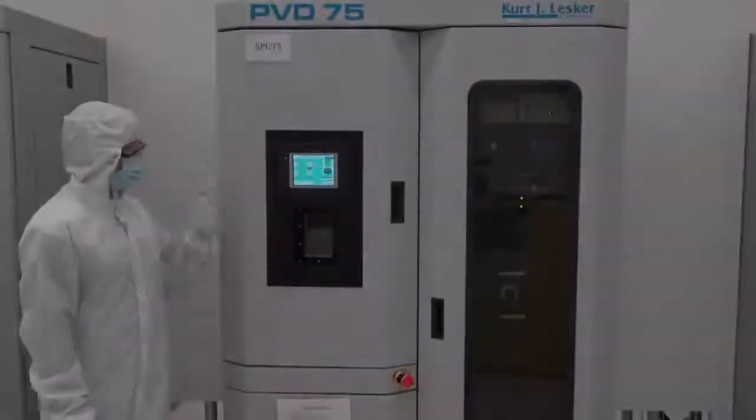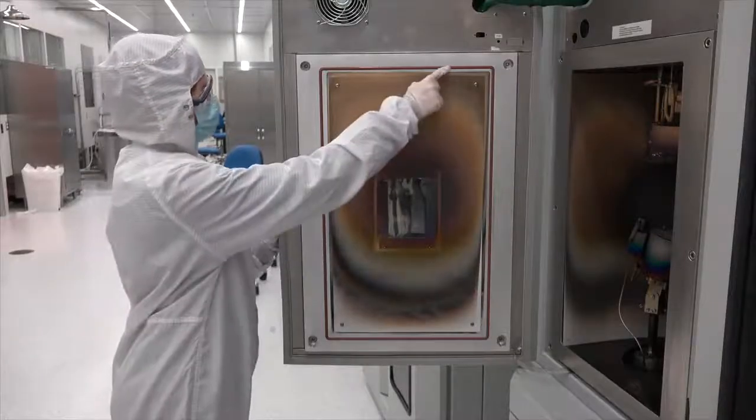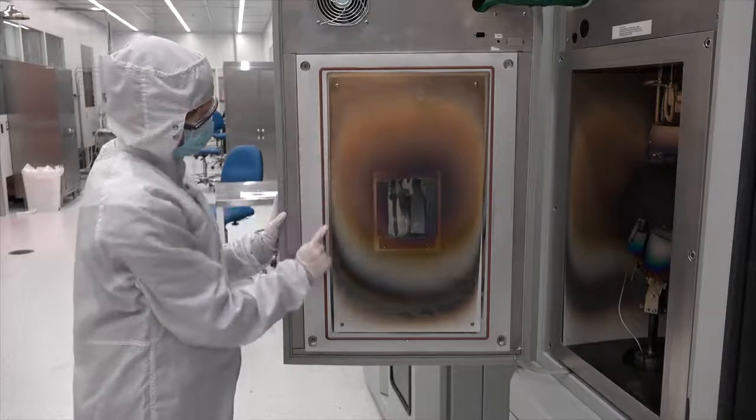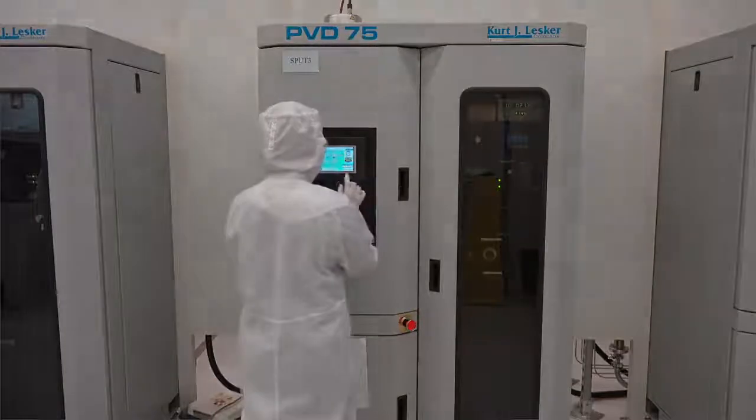Hey, Callie. I understand that you're making some photodetectors in the clean room today. Now, a photodetector is an electrical device used to detect light and output an electrical current. Callie, can you take us in and show us the vacuum system that you're using to deposit the contacts onto your photodetector? Sure, I'd be happy to. Let's gown up and go into the clean room to see the system. That sounds great, thanks. This is a metal deposition system, and we can see the place inside where the vacuum pumps will remove the air from the chamber. This orange rubber ring is a vacuum gasket that seals the chamber from the outside air when we close it. Let's close it now, and we are ready to pump the chamber down to vacuum.